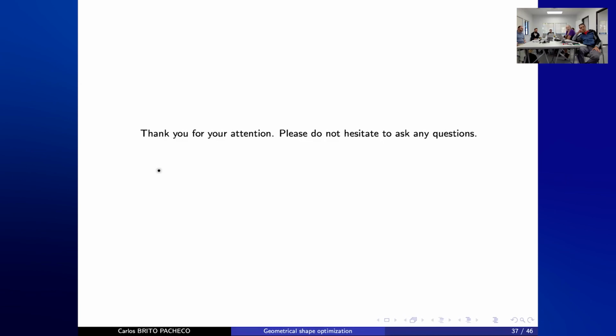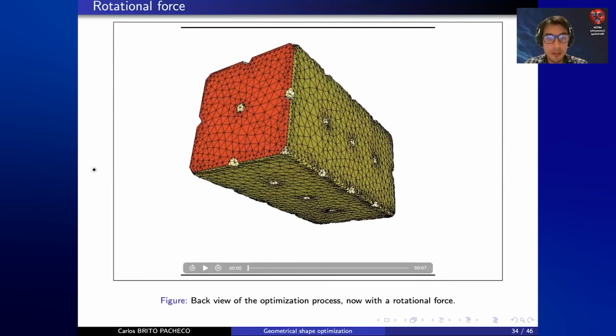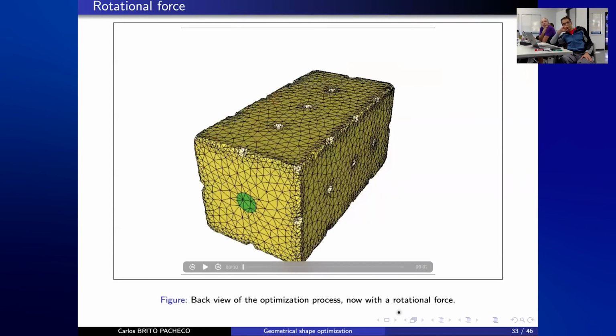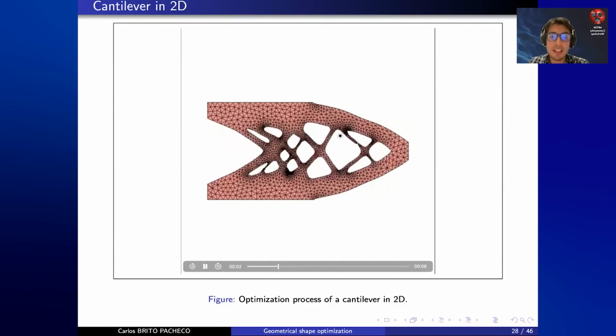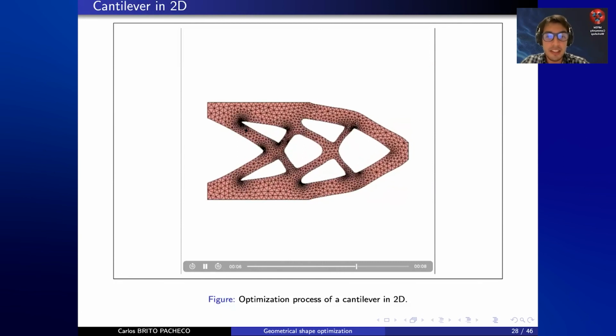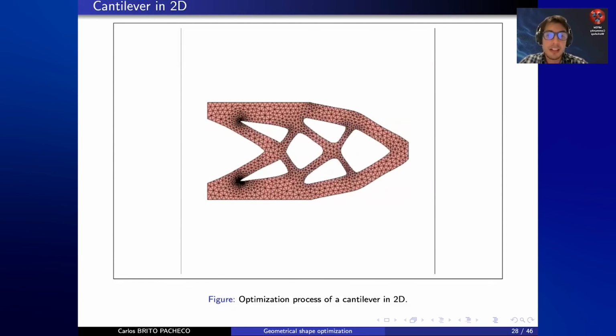We were wondering, are you remeshing at every iteration? Yes, I am. Thank you for your question. I generate the implicit domain mesh of the level set function, and yes, there is a mesh optimization process that is carried out. However, the mesh is known beforehand, so there's only splitting involved.